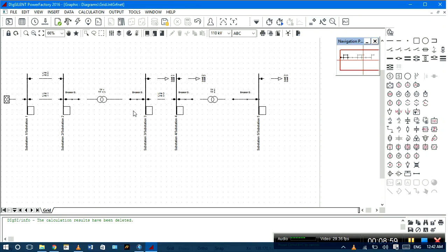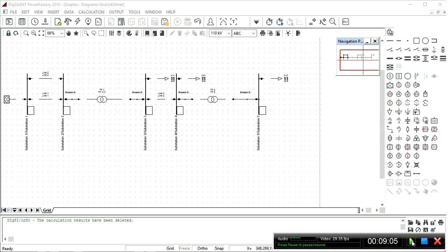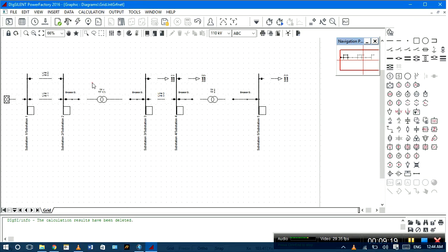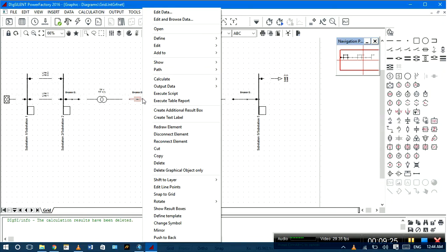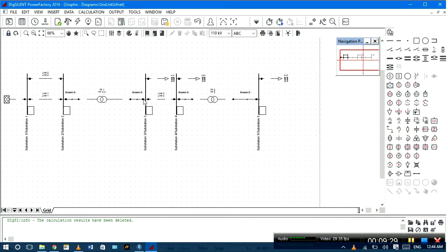So how do you do that? The first step is to set up a current transformer at this bus bar. Why? Because I have chosen to set up my differential relay at this cubicle. Similarly, if I had chosen to set up my differential relay at this cubicle, I would need to define a CT before I can do anything else at this cubicle.